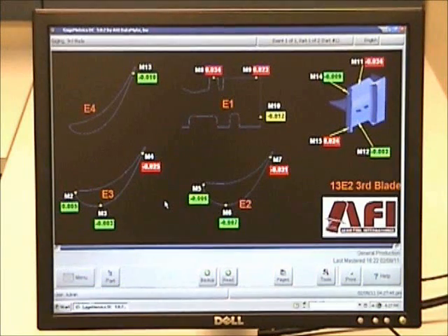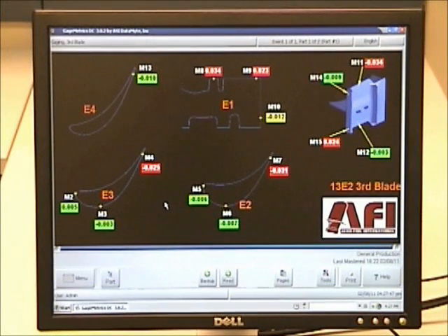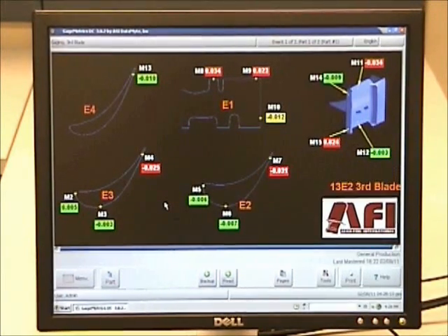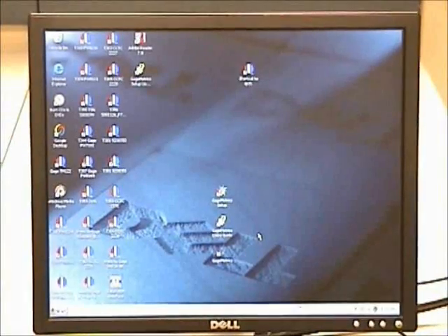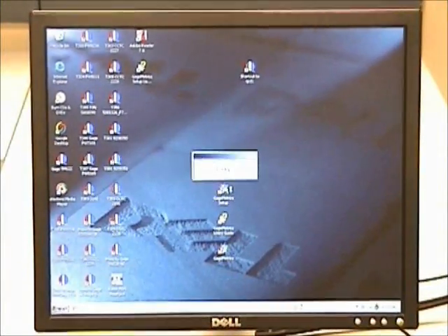What you see on the screen currently is measuring that exact casting. You'll notice green, red, and yellow. Green is obviously good and within part limits. Yellow is a limit, would be crowding outside of your upper or lower specification limit. And then red is out of tolerance, whether it be in a negative or a positive value. The upper and lower spec limits are something that you can set, and we'll go to that screen in a minute. All right, we're going to go back into GageMetrics setup, which is where the programming happens.